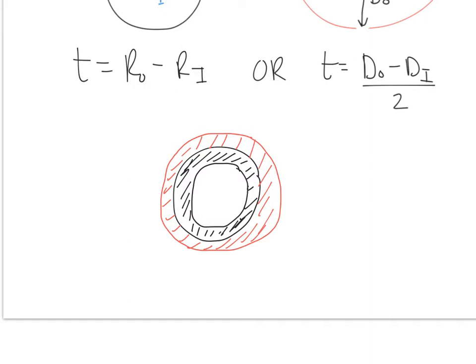We'll see this better when we do CAD work. You'll see this a lot. You'll see an ellipse if you cut through at an angle. But if you cut through perpendicular to the pipe direction, you will get an exact circle, and you'll get concentric circles like this. Now, let's say I wanted to figure out the amount of PVC needed to make this pipe. To do that, I'm going to need to know how much area the PVC makes up, and then I'm going to eventually multiply it by its length to get the volume.